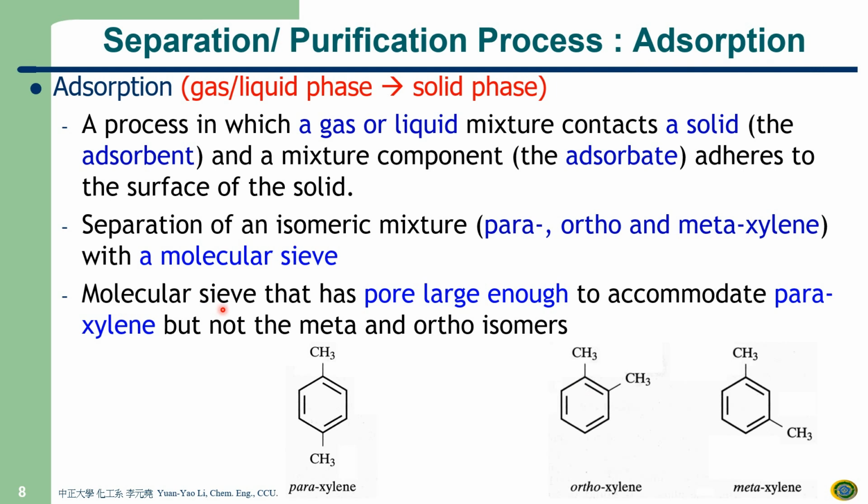So we use molecular sieve. The pore is large enough to accommodate para-xylene, but not the meta and also ortho. So this one will stay in the molecular sieve, and these two will be free to remove.